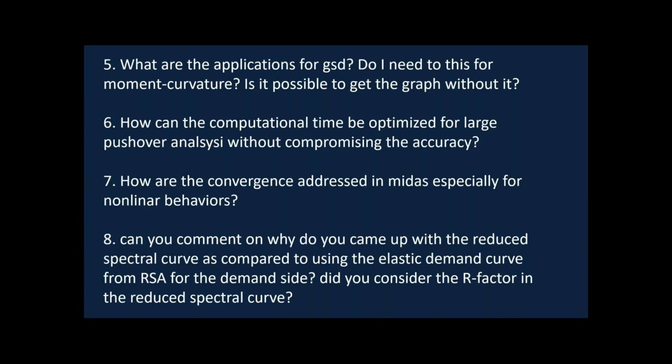To ensure the same damping, we know that as the seismic event happens, the structure will be damaged and the damping will increase. So we reduce the demand on the structure by increasing the damping. We know that the higher the damping, the lower the demand on the structure, because as we increase the damping ratio, the demand curve reduces, or the spectral acceleration reduces.